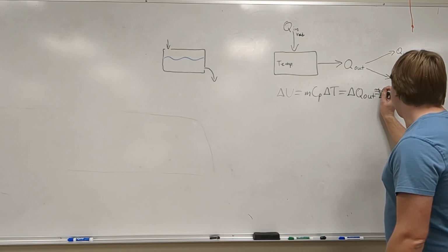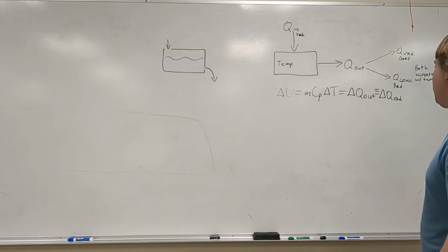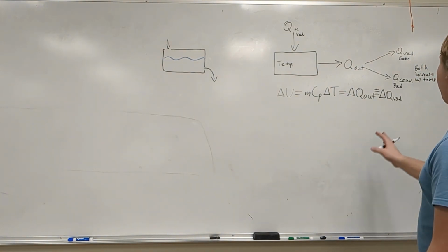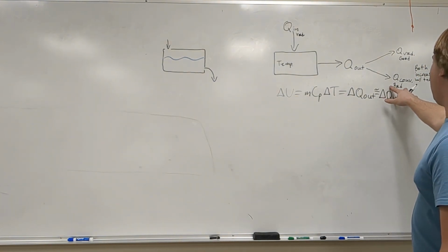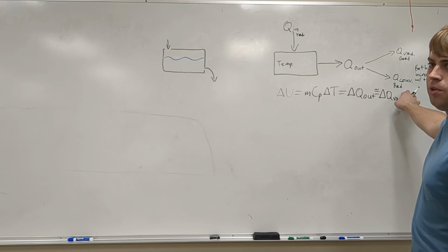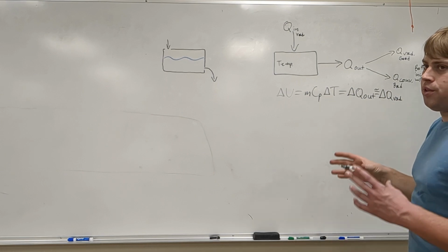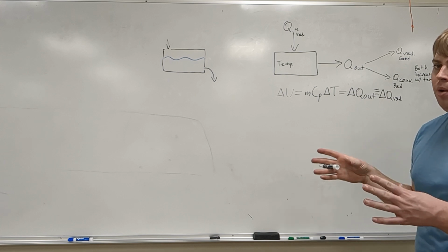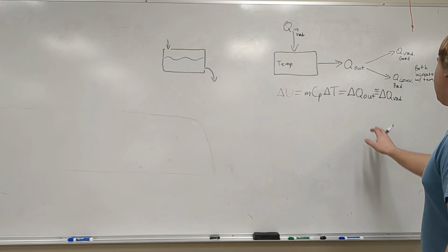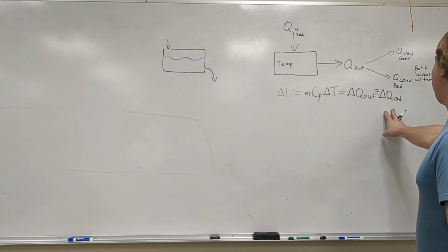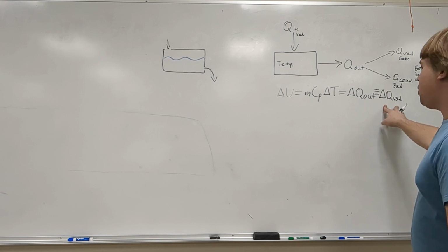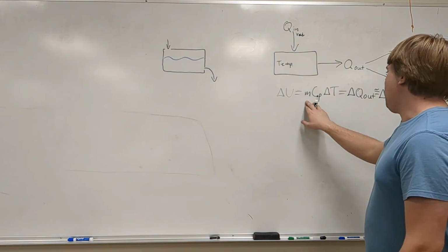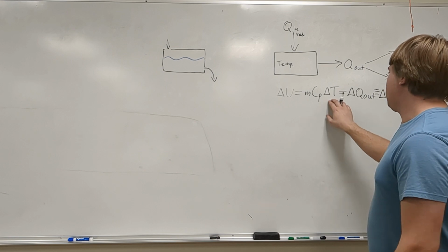We can compare between the two because both models were in the same area under similar conditions, with about the same geometry, so the convection coefficients are almost the same. We are looking for change in Q radiation by looking at the difference in mass times heat capacity times change in temperature.